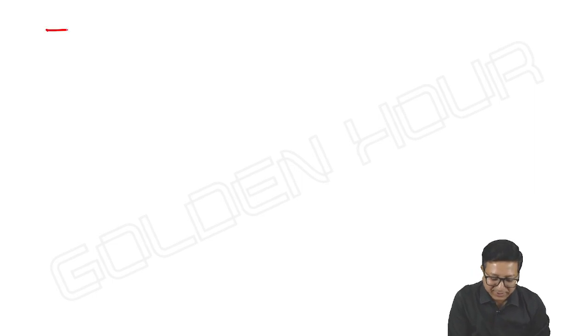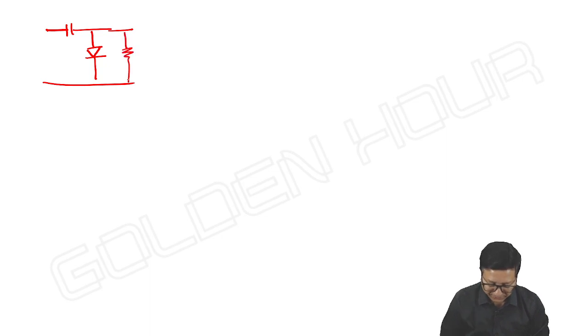So far, we have seen the basic negative clamper circuit, unbiased as well as biased circuits, in which I assumed the diode is ideal. If the diode is not ideal, then what will be the output? See this. If I take this basic negative clamper without reference voltage, the unbiased case, first let me write without the resistor. Next we can use the resistor and continue it.